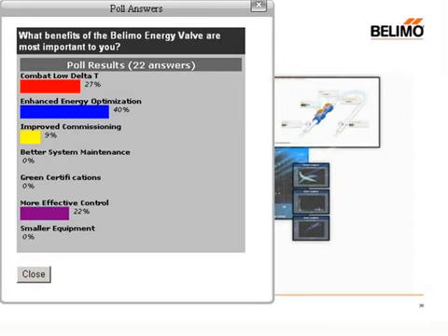The operator has the opportunity to do that if they want, but we're not recommending that. That is the design delta T for the cooling load. So we're not asking the valve and the delta T to do anything more than the design condition, which was the 99% degree day situation.